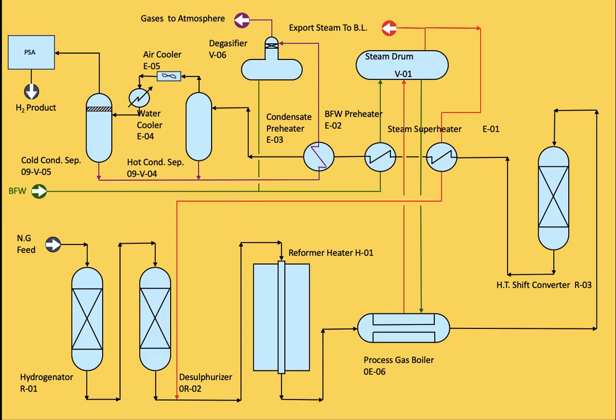Then the reformer furnace, which is tubular, and as we saw in the diagram, it can be up-fired, side-fired, or terraced. And then you apply heat recovery and produce steam, then the shift converter and cool the stream, then the PSA to make what? To remove the residual CO2 from the stream and give you hydrogen with purity around 99.9.